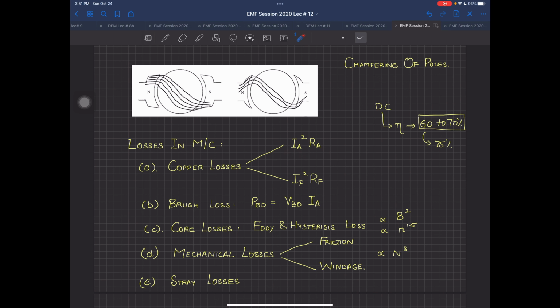And you all know the formula for the resistance based losses, which is I square R. So you can see this is the armature winding loss and this is the field winding loss over there, based on their currents which are flowing. Now these are equally applicable for your shunt machines. Over here, the shunt machine armature winding, the shunt machine field winding. But overall, when I'm talking about the series field winding, I guess you are already familiar with this, that the current which is flowing inside a series field winding is called IA or ID, totally dependent upon which variable you are using. So for a series machine, these losses are going to be called IA square RD.